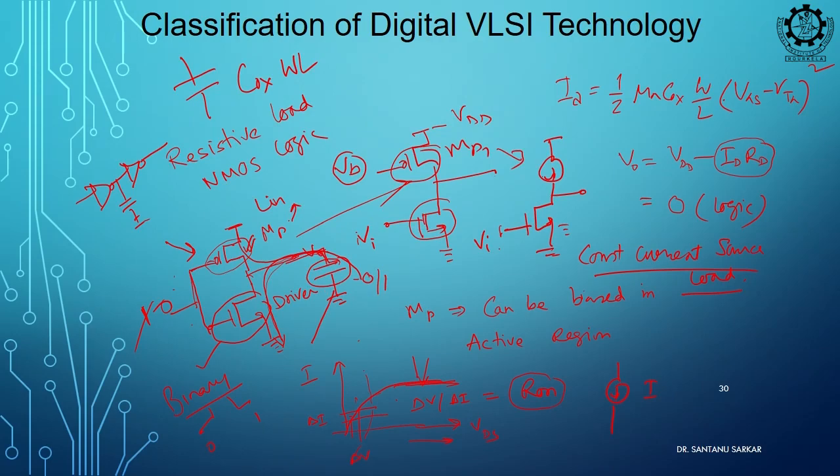Now, will this voltage discharge? The moment this capacitor is discharged, again this current path will charge it on. So, you see from the VDD and ground a strong connection always exists. So, that is why it is known as the static logic. Okay. But same will not be there in the dynamic.